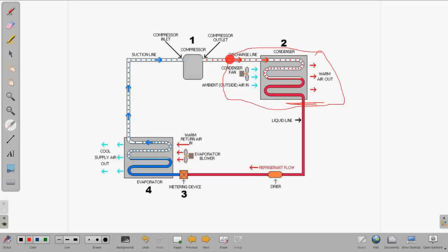So at this point, we start to reverse the refrigeration process that happened in the evaporator coil, and we have all vapor entering the condensing unit. Then what starts to happen as it passes through the condensing unit, the outdoor air, which is cooler than the 110 degree or so vapor, the refrigerant starts to change state back to a liquid state.